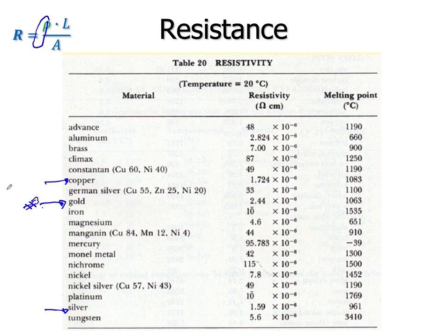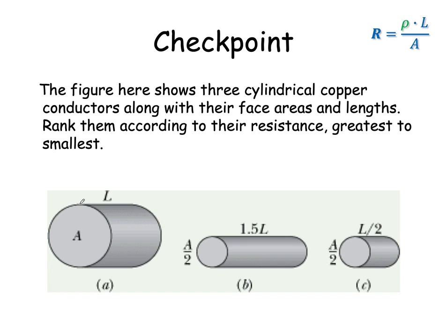The answer is, if you haven't already figured it out, gold doesn't form oxides or chlorides or sulfates, whereas copper and silver do. So even though pure silver and pure copper are better conductors than gold, in reality, when copper and silver are exposed to air, they tend to oxidize, or in silver's case, create sulfates. And those salts are not electrical conductors. So we tend to coat things with gold, and it's not the best conductor, but we don't have to worry about it oxidizing.